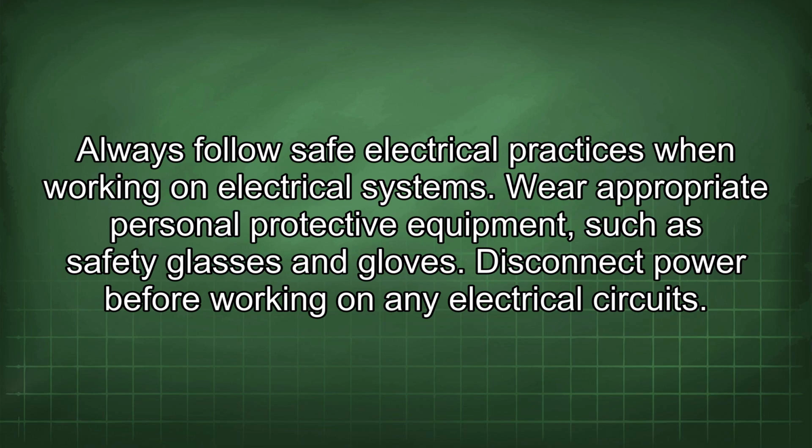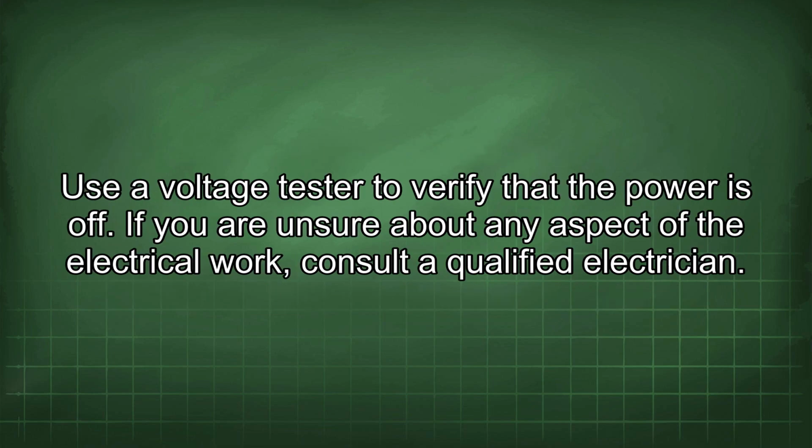Wear appropriate personal protective equipment, such as safety glasses and gloves. Disconnect power before working on any electrical circuits. Use a voltage tester to verify that the power is off. If you are unsure about any aspect of the electrical work, consult a qualified electrician.